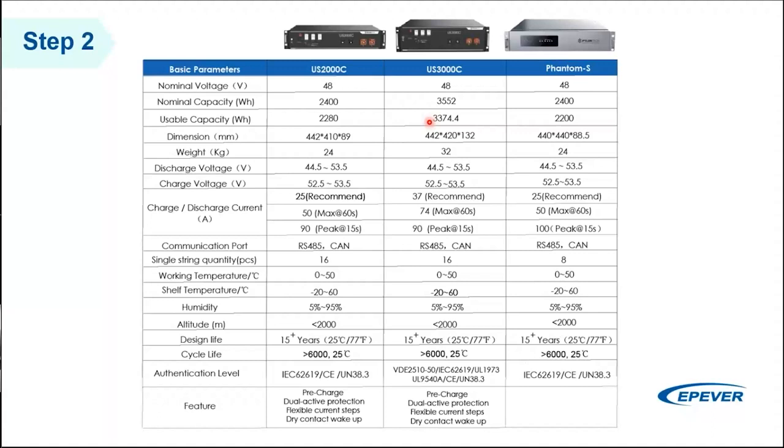It could be 1 battery for smaller systems, and they are modular, and you can put them into a rack, and you can easily expand the capacity of the system. That's why I prefer to use these type of batteries in my example. And these kind of batteries have a self-designed BMS in their system, which protects the cell in a variety of aspects, such as harsh temperature, the current, over voltage, etc. So your battery is safe.